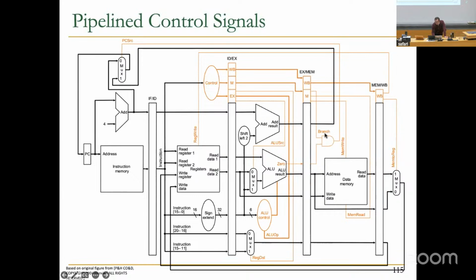Memory stage, some controls, like branch, whether this is a branch, is needed because we calculate the branch condition in the previous cycle, like that's 0. If what we're processing is a branch, and the branch condition is satisfied, meaning it was 0, then we basically set PC source to 1, which means that we get the PC from the target address that was computed earlier, right? So there's no magic. We've actually built all of this data path. The data path is already there. We just delay the control to the appropriate time, right? Does that make sense? Okay, this may require some more thinking and going through the figures, but essentially, this is your single cycle processor divided into different stages, control signals delayed to the appropriate place.